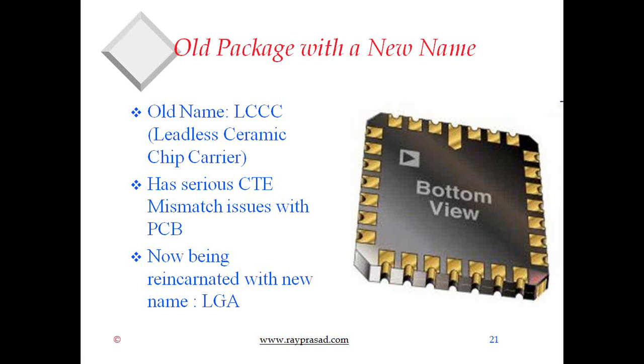What you're looking at here is a leadless ceramic package with gold-plated leads, and these are what are called castellations on the side. As a matter of fact, this was even a better package than BTC today because you can get the side fillet, because think of these terminations, where my arrow is, as half of a hole that goes through the thickness of the package.